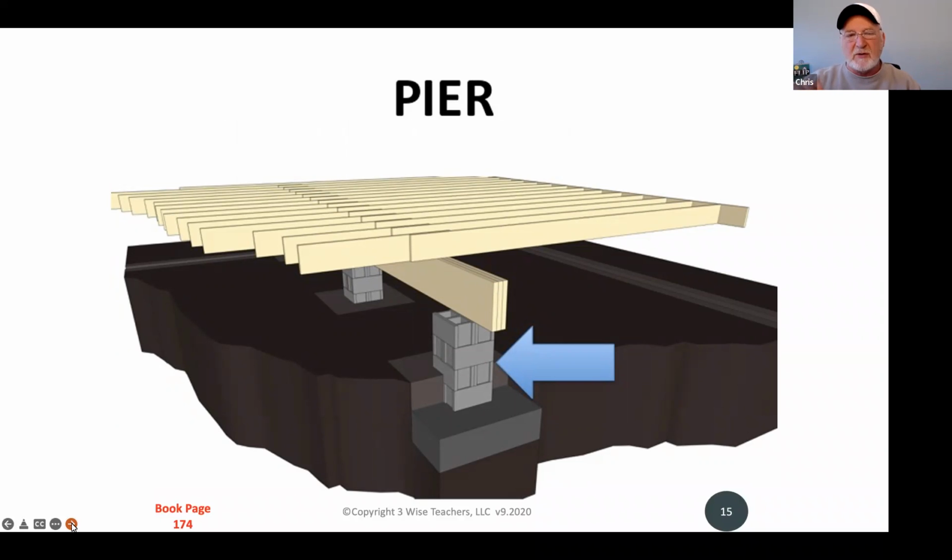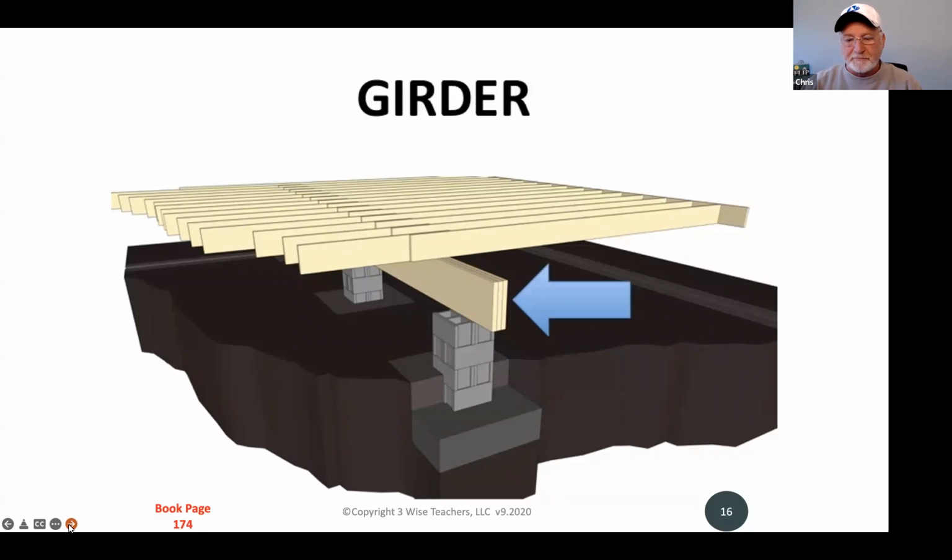Well, hopefully you can tell from the picture here that oftentimes you have wooden components that run long spans. So the piers are put, you can picture in your mind, halfway in between the two exterior foundation walls. And so it's there to support. When you see the pier, they're talking about that concrete structure that's built on its own specific footing, and it's there to support the middle of the house. It's inside the foundation wall.